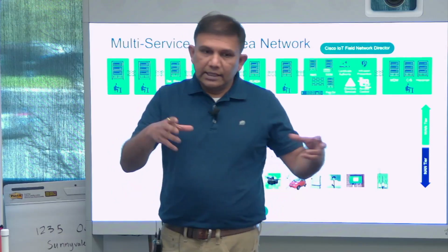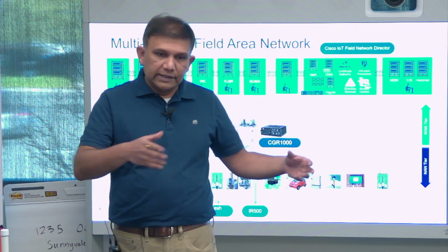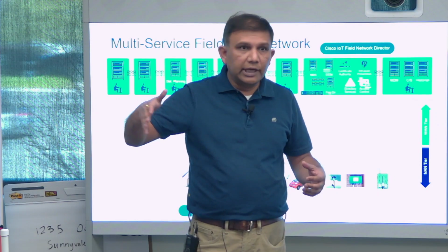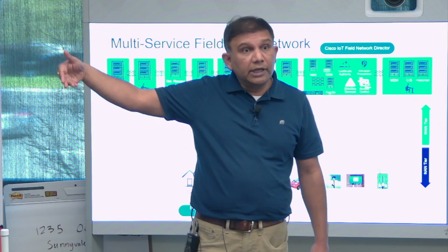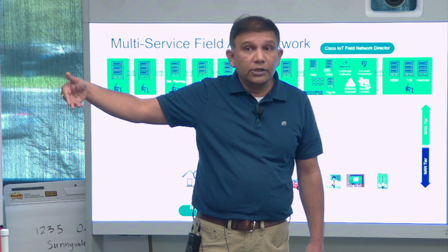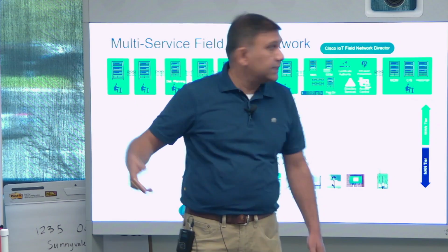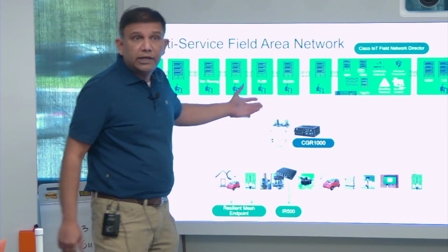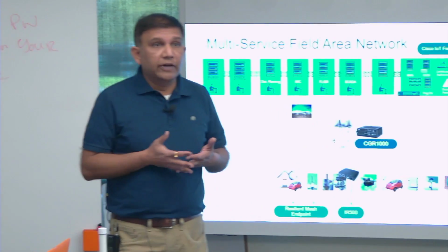Right. And so there's a very different paradigm, at least for the SCADA side of it. Yep. So once the serial protocol is transported over the IPv6 network, it basically terminates in the head end, where the SCADA system, like the DMS system here, can communicate and control that device. Right.